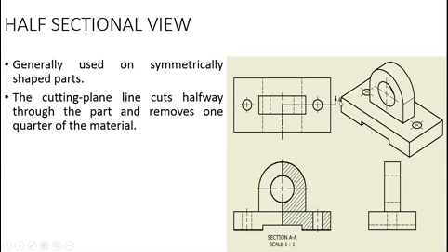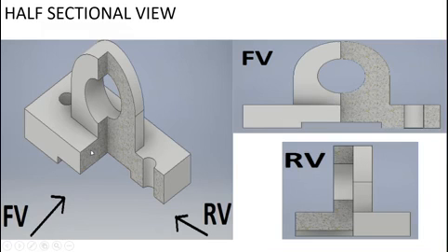Okay, the same way with the arrows, after cutting we have to look at that side, the arrow of the cutting plane, so it is pointing upwards there. Then if we look at the 3D drawing now, you can see that we just cut it from there, going to the center and then coming back there. So we have cut this 1/4 of the drawing here, and now we have to look at this side. We're going to take this as our view because the cutting arrow was pointing towards that side. So this is where we have to view the drawing.